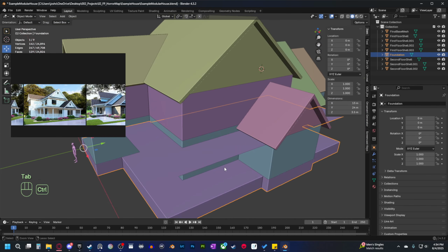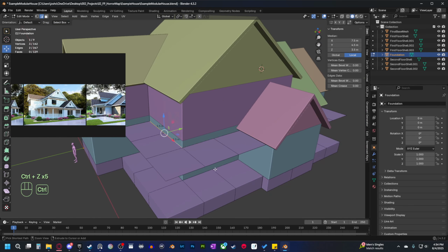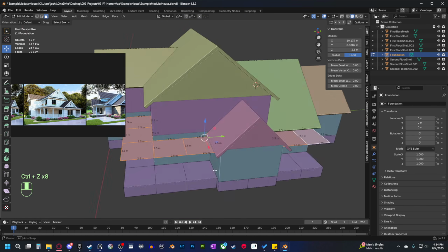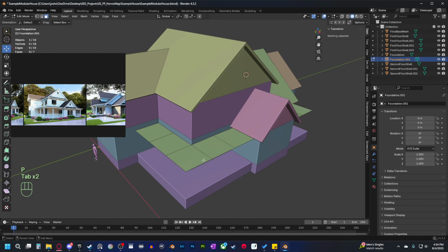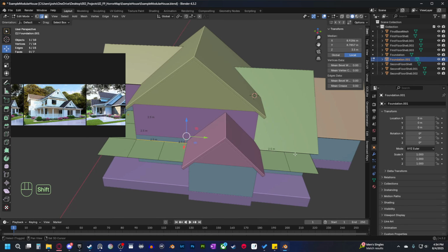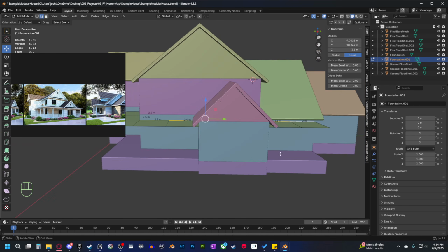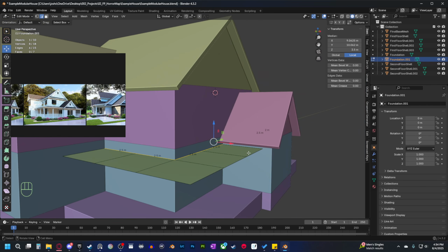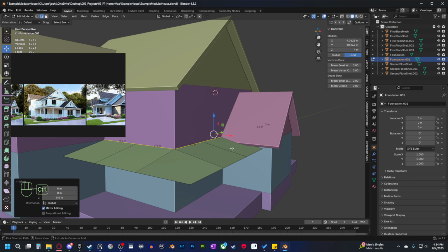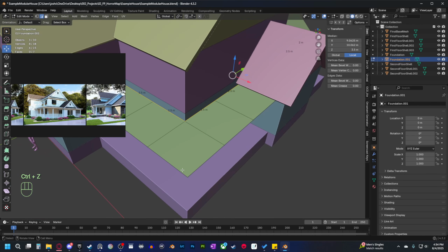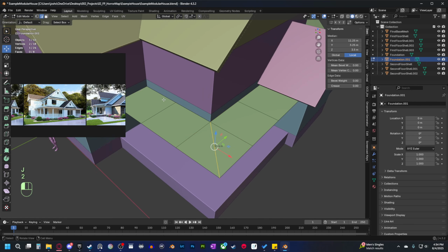And then I'm going to select the edges. Let's see. Oh, hold on. We need to actually separate this. Okay, so now I'm going to select just these back edges, like so, and we're going to raise that on Z by 0.5. Oh, and I'm also going to need, let's see, we'll need a loop there, so I'm going to connect those with J.